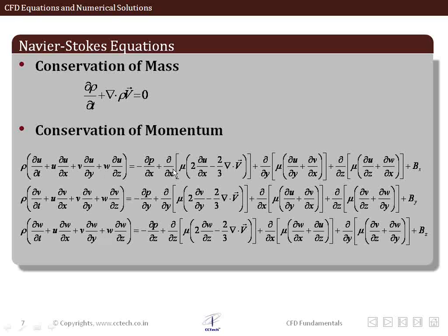And we have on the right hand side, in addition to the viscous terms, also a pressure gradient term, which is also present in the momentum equation, and the last term being the source term or the body force term, because we are speaking about the momentum equation. So we have a representation of mass into acceleration being equal to the sum of the surface forces, that's the pressure gradient and the viscous terms that you can see here, plus in addition to this we also have the body forces, which is acting on every point inside the domain.